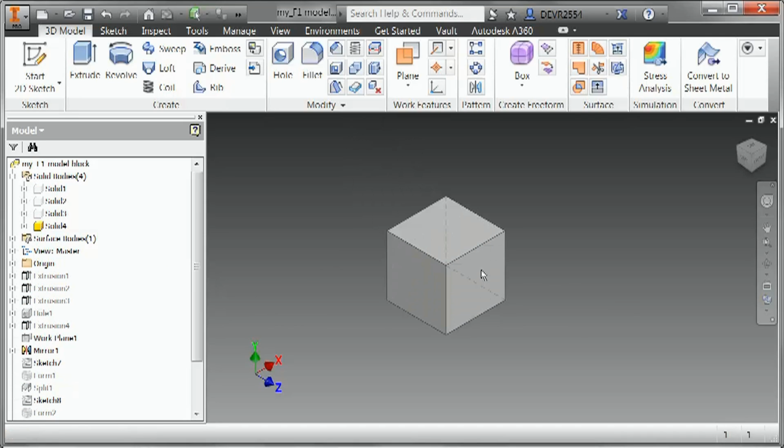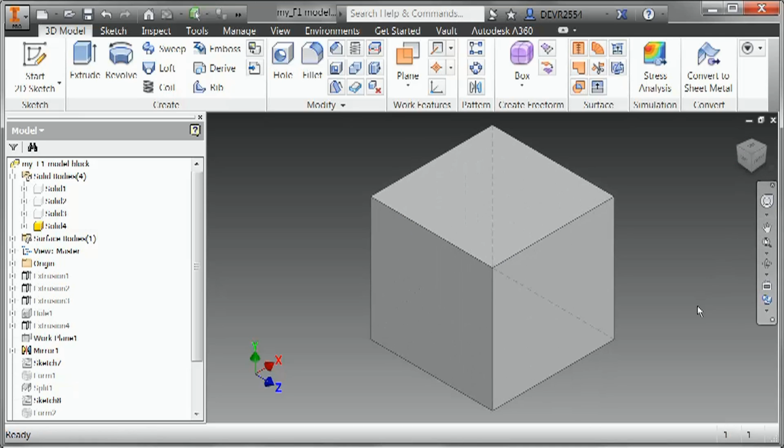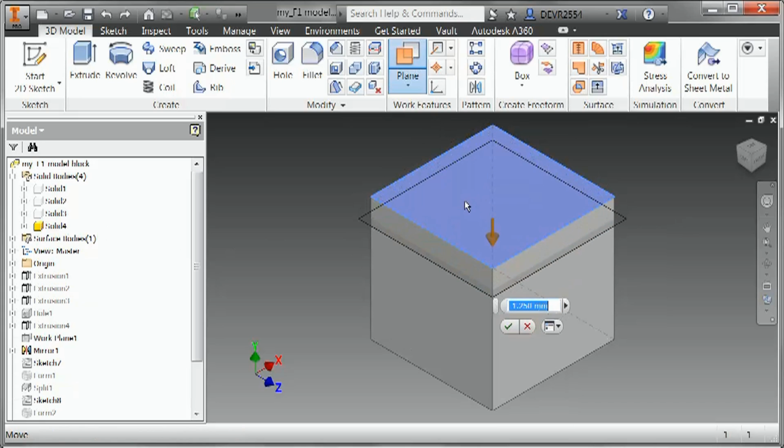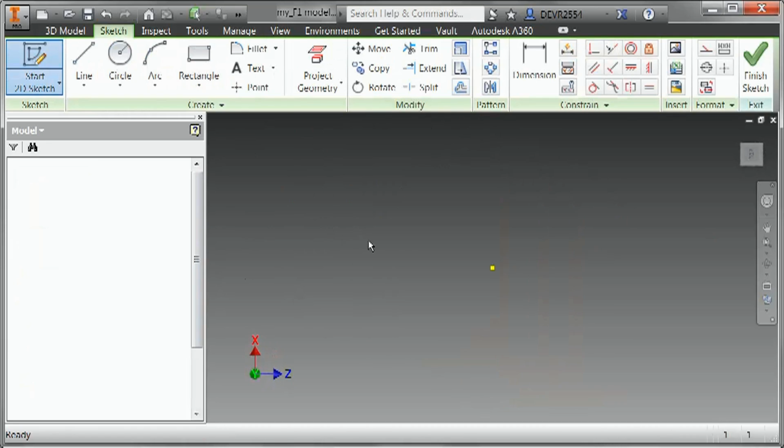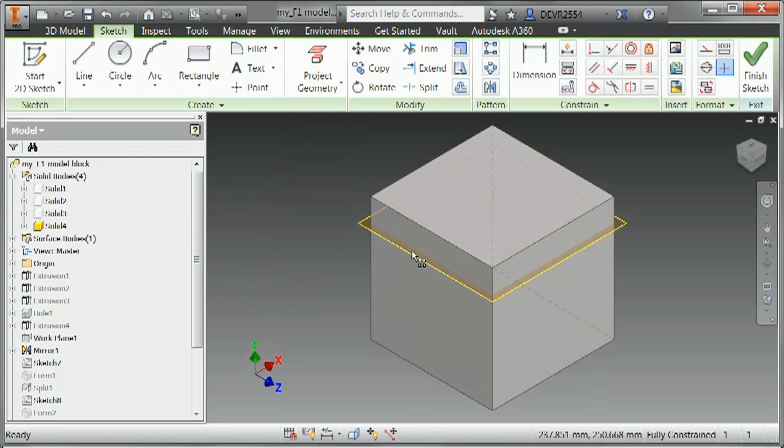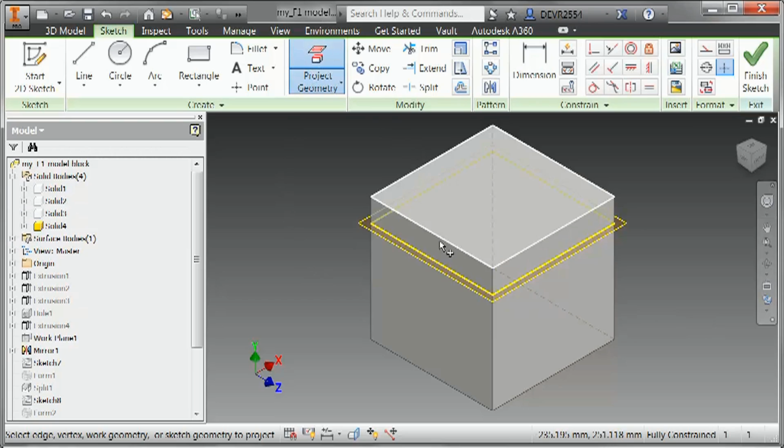What I want to do is hide all the others. I want to work on that little extrusion. I'm going to affect a little collar around it, which will actually be tied to the rear wing. So I'm using the extrusion to help me build that. Create a work plane, drag it down -1.5, and that work plane is going to be the basis for the sketch I'll create. Just press the F5 key, it zooms out to the whole car, and on that tiny little piece, by pressing F5, it brings it back immediately.